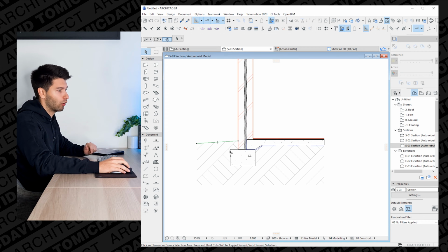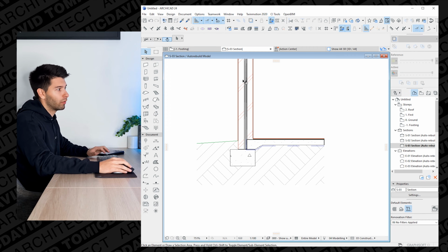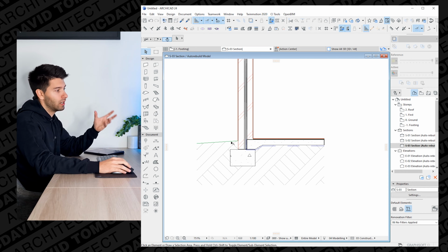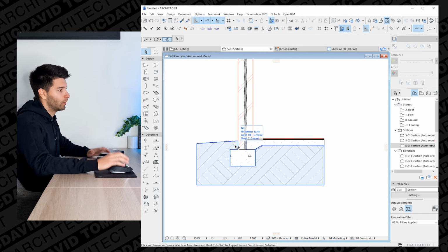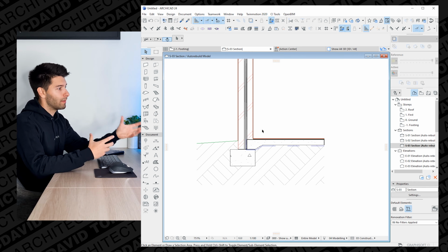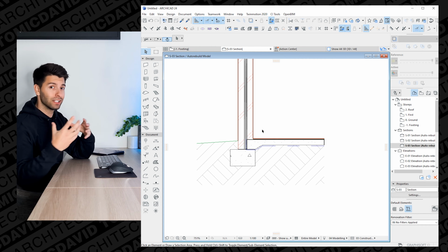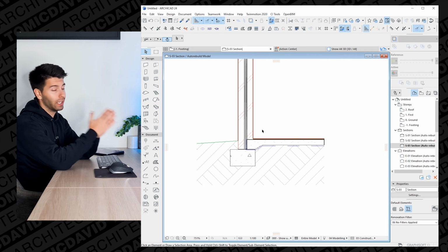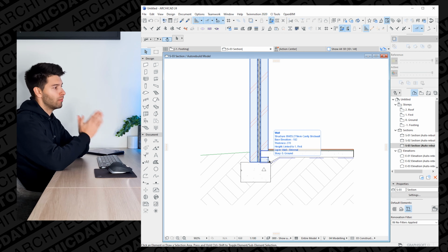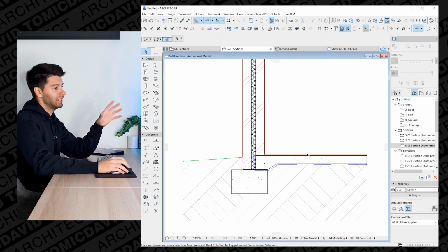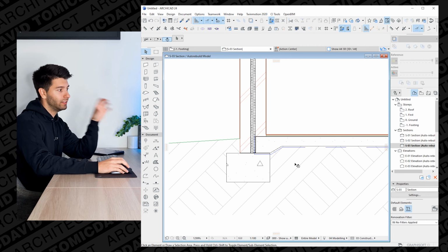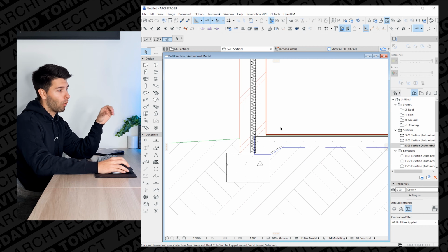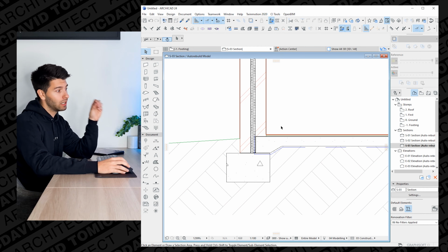We can point to the mass concrete footing, point to the external brick wall, the cavity, filled insulation, and all sorts of other details when we detail it further. But we're not going to go into that much detail on screen, because like I said, I like to articulate this and explain everything as we go through it. But there we go. That's basically our concrete detail from a structural point of view of how a double brick cavity wall sits on a concrete footing with a concrete slab.